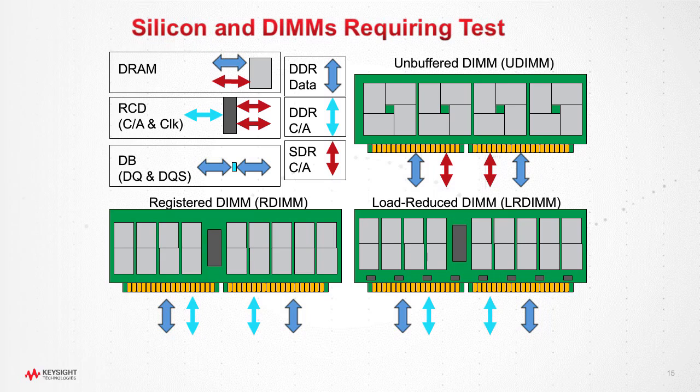So at these interfaces, some of them are running at high speed, some at lower speed. Obviously, signals like reset would be very low speed, and the data bus will be at the highest speed. The way the spec is written for each of those and the way the measurements need to be done is going to be largely driven by the speed at which they operate.